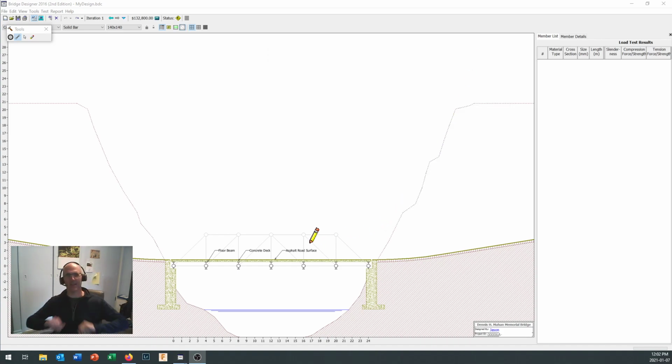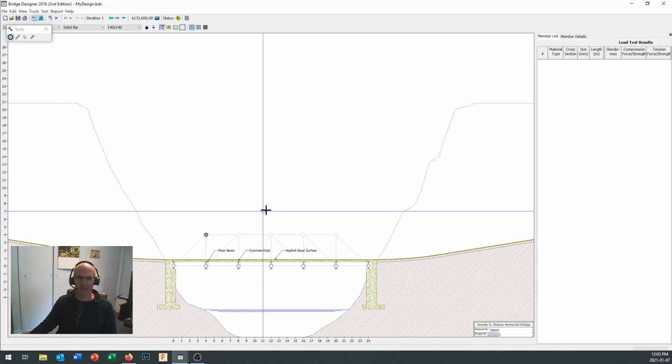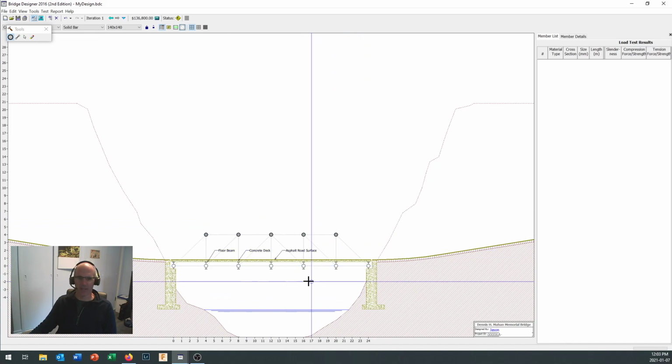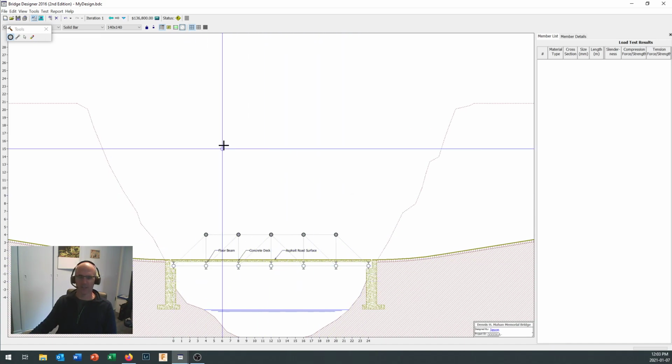Okay, I think that sets up where I want to get to for setting this bridge up for you now. So here we go. We've got a truss template on here, and you can come along and add some nodes. We're going to be talking about nodes quite a bit. The nodes for the deck of the bridge are already installed. Nodes are really important when we're talking about trusses because the defining aspect of a truss is that it's held together by pinned joints.